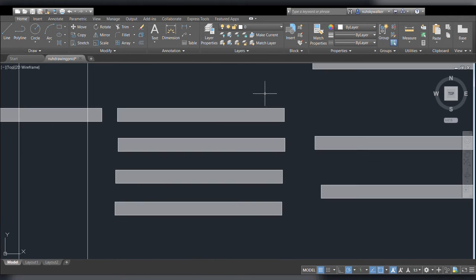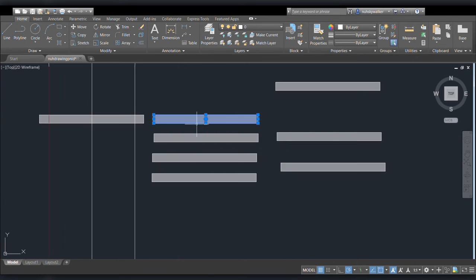If you would like to move this thing, I forgot that we will need to pick or select this particular object from the right, like this, so that you'll be able to select the entire lines, because this particular rectangle is made up of 4 lines, remember, 1, 2, 3, and 4. Another one is right here. So 1, 2, 3, 4. So you have to select it from the right, so that you'll be able to select all of the related lines.